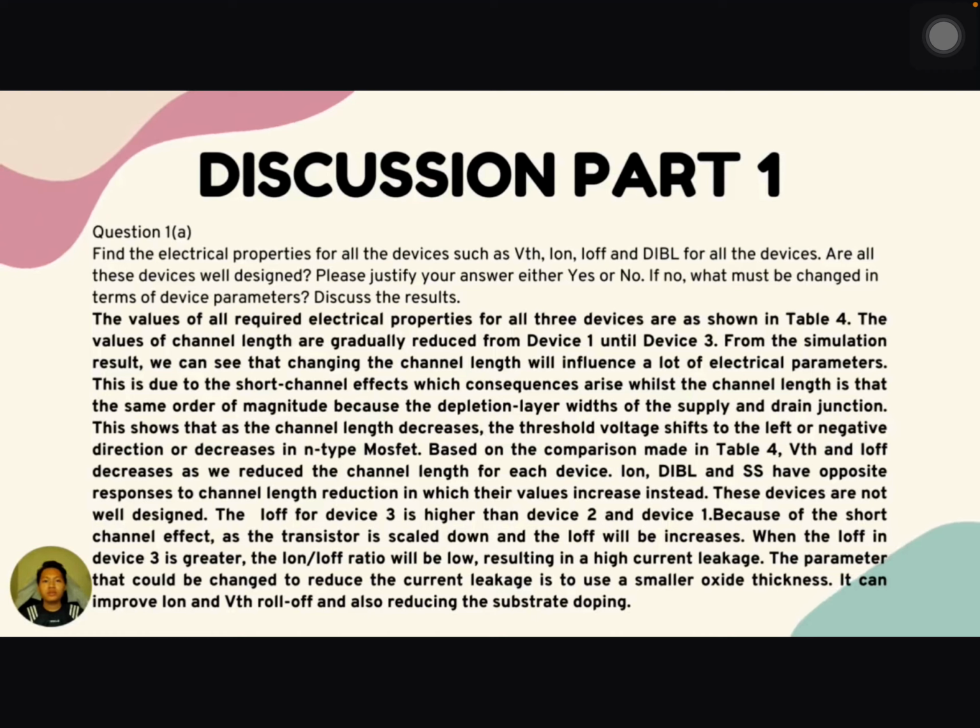This is due to the short channel effects, which arise when the channel length is of the same order of magnitude as the depletion layer width of the source and drain junction. The electrical properties changing is due to the short channel effects. The parameters that could be changed to reduce the current leakage are to use a smaller oxide thickness, which can improve I on and threshold voltage, and also reducing the substrate doping.